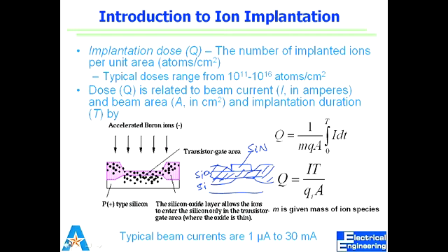But once they get incorporated into the substrate, then it's a three-dimensional problem. And it starts so simple, just because when we strike the beam, it's in vacuum. There is hardly any resistance or hardly anything that impedes the flow of ions. But once they get into the substrate, the physics changes. So then it's a 3D distribution problem.